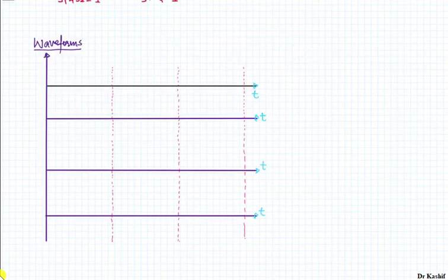Now we quickly draw the waveforms. First of all, we draw the gate voltages, base voltages, or the control pulses of your switches. So let's suppose that our switch S1 is turned on, and so you will have to apply the gate voltage. Let me call it VG1, right? The voltage applied at the gate of your switch 1.